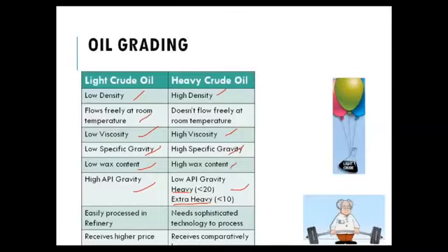If it is less than 10, it is extra heavy. If it is less than 20, it is heavy. Light crude can be easily processed in a refinery and receives a higher price, while heavy crude needs sophisticated technology and receives a comparatively lower price.